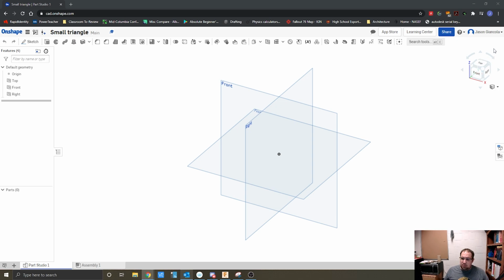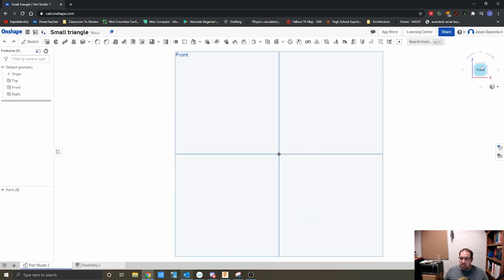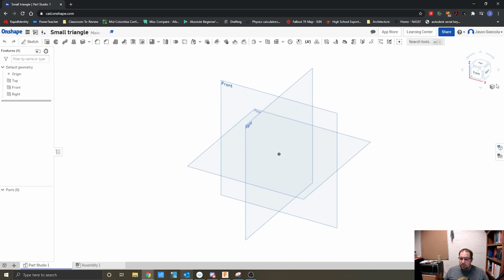The next major thing that we want to look at is our view cube. Our view cube, we can grab, and we can move it around. Then we can actually adjust which way we're looking at it, how to switch from one side to the other side. So if you hover around that gray outside, it switches to the opposite face that's showing. Okay. You can also change the style of it over here. We'll talk about that later. Okay, because sometimes you'll want to do shaded or shaded without edges. For the most part, though, you want to leave it shaded with edges. You don't want to do the shaded with hidden edges.